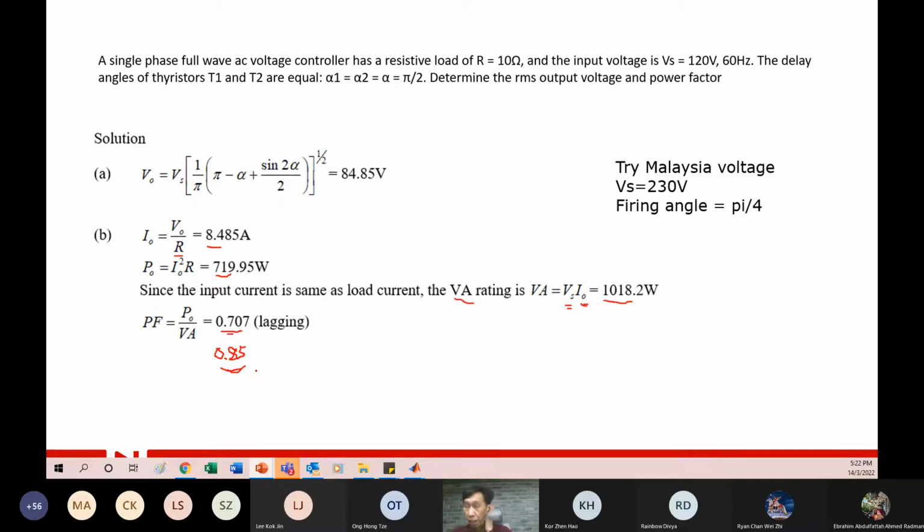Especially if they have a light dimmer system to control the lighting. So what happens is that they will end up with a power factor like this one, very low. And every month they get a penalty, and they don't even realize it, because the contractor just says, oh, you want a dimmer for all your restaurant lights, can, he just connects it for you, right? It's not his responsibility to tell you that you will get all these charges, okay? And then